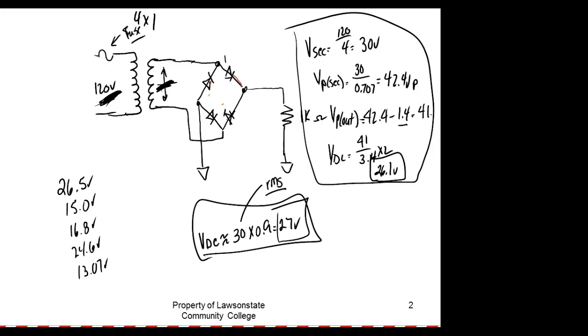Here I think we've got 112 volts here, which is still within perfect limits of what the National Electrical Code says is legal. So this is why when we give these calculations, we're going to give you 120 volts is what we use most of the time. Of course, because that's what the National Electrical Code says is the nominal voltage. And that's what they use all through their whole thing, 120 volts and 240 for residential wire.